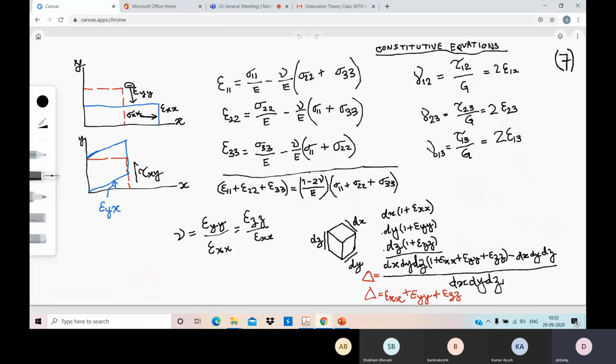Similarly, if I give you stress tensor, you can calculate strain tensor. If I give you strain tensor, you can back calculate the stress tensor, and from that you can derive whether yielding will occur or not. So if you see in a body some amount of displacement, because we said that ultimately the thing that we measure is displacement. Inside a bridge, we put certain gauges.